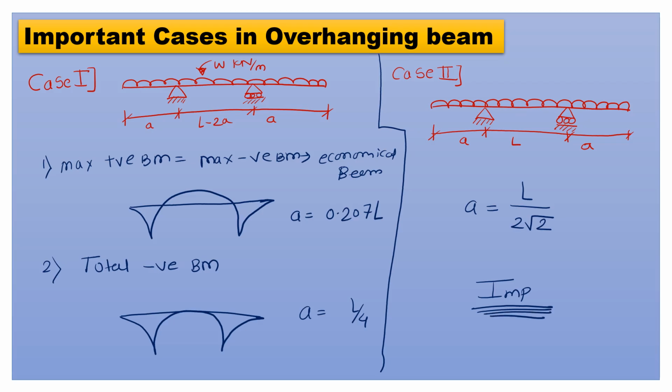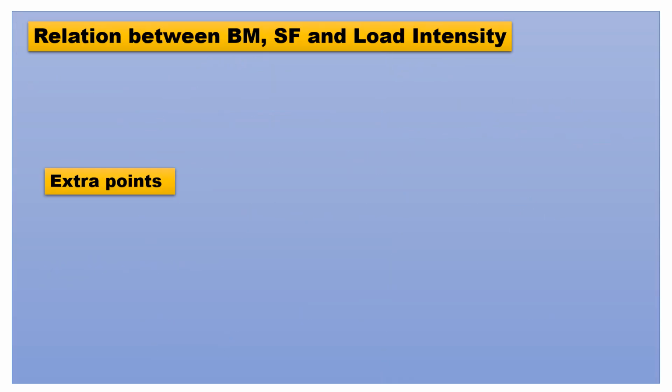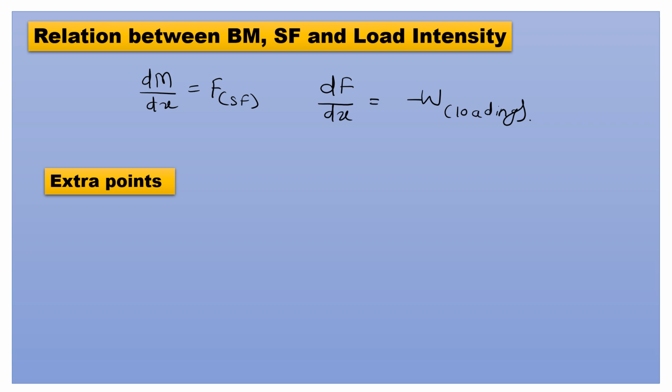Important question. Remember this question and values of A for different conditions. Relation between bending moment, shear force and load intensity. The derivative of moment is nothing but the shear force, and the derivative of shear force is nothing but the minus of loading. So this is the relation between shear force, bending moment and load intensity.